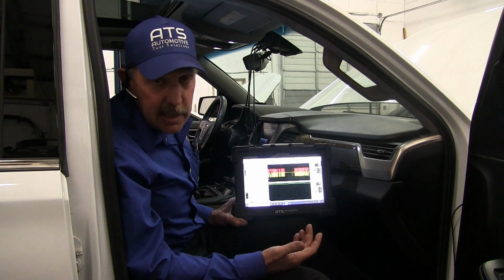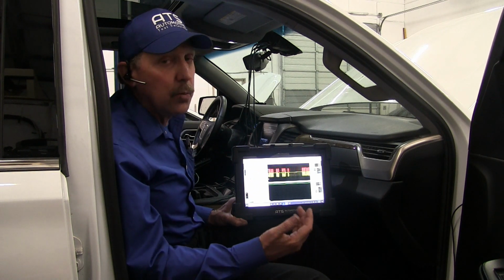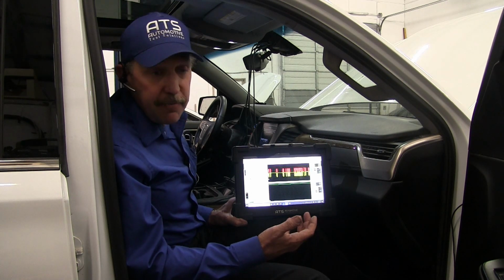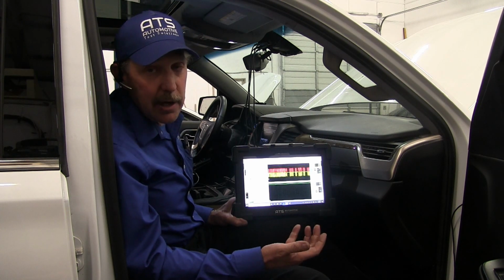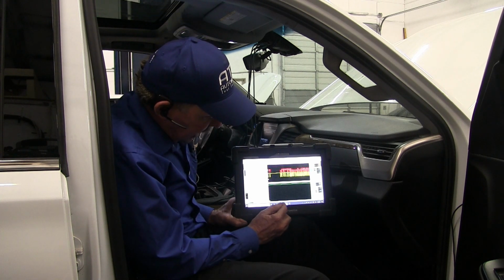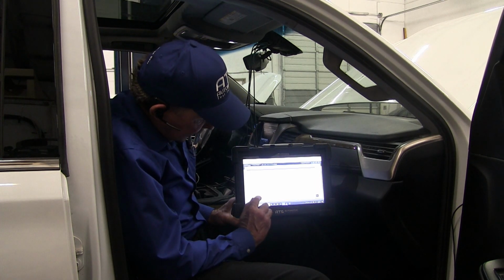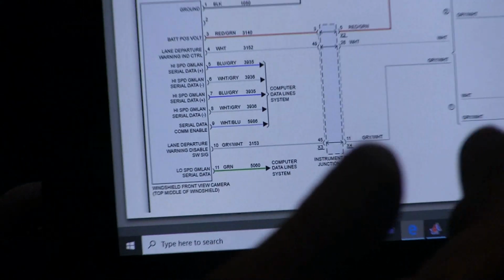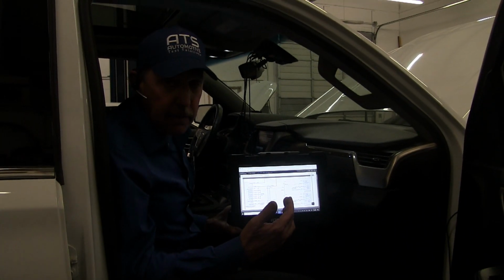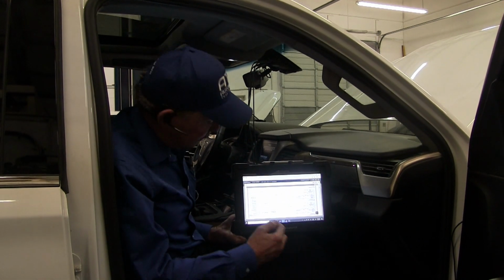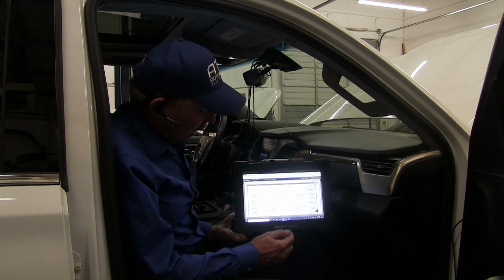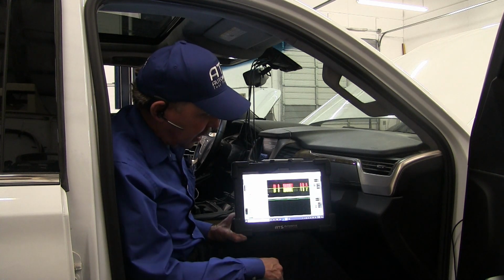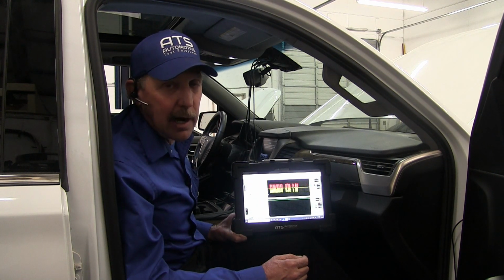Now the really crazy thing is the wiring diagrams could really confuse you, because when you look at the data for the communications, that wire's not even in there. When you come back and look at the data, it just says that it goes to the COM lines, but it really doesn't show it. You go back to the communications structures for the wiring diagrams, those wires aren't even there. So that wire is present because I'm back probed and there's nothing on it. So let's go ahead and bridge that wire and see what's going to happen.